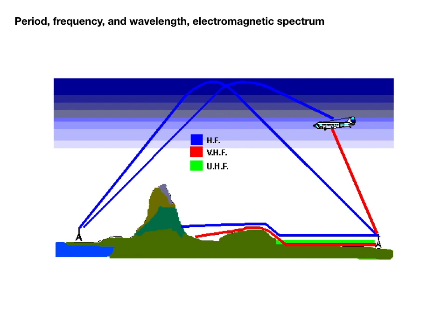Radio waves at higher frequencies, such as those in the VHF, UHF, and microwave frequency ranges, tend to pass through the ionosphere. That's why we tend to use them more for local communications or space communications rather than long-distance worldwide communications. This is one of the reasons that most repeaters operate in the VHF and UHF portions of the radio spectrum. Cell phone systems also operate in the UHF portion of the spectrum.